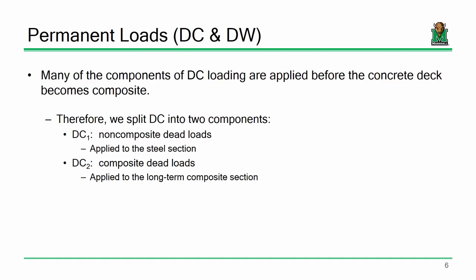Now, one other thing I should point out, and I guess I should have included it on this slide, and you're more than welcome to put it in your notes, but maybe it's a good thing I didn't, because now I can pop quiz you. DW. You think DW belongs on the short-term composite section or the long-term composite section? Long-term, it's always there. It's permanent. So if you want, you can put the little note there on the bottom that DW belongs on the long-term section because it's always there. Right, so far, so good?